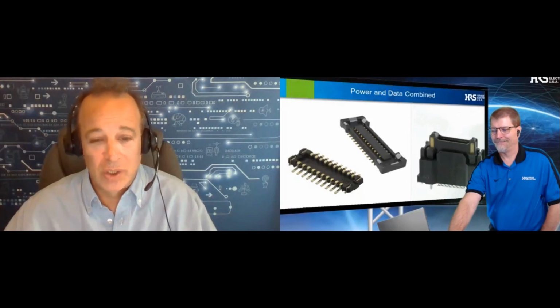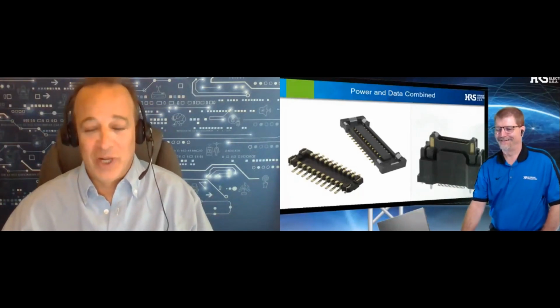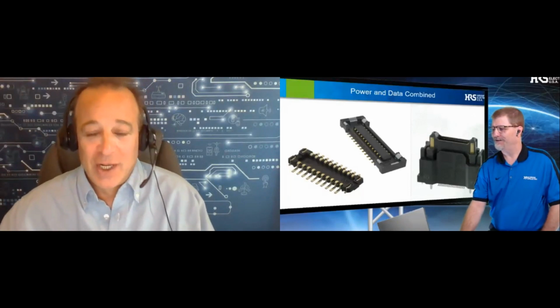Going once, going twice. Oh, we have another question just in time. All right, here's the question. If the ambient environment is cooler than 25 degrees C, can we pass more current than Hirose's recommendations through the connectors? Awesome question. When you want to push the envelope on a connector, we're going to want to know about that. The reason is there are other factors with regards to the contact itself and how it dissipates that heat. So even though the ambient is lower, and you're right, that means that you can, in theory, dissipate more heat to the environment.